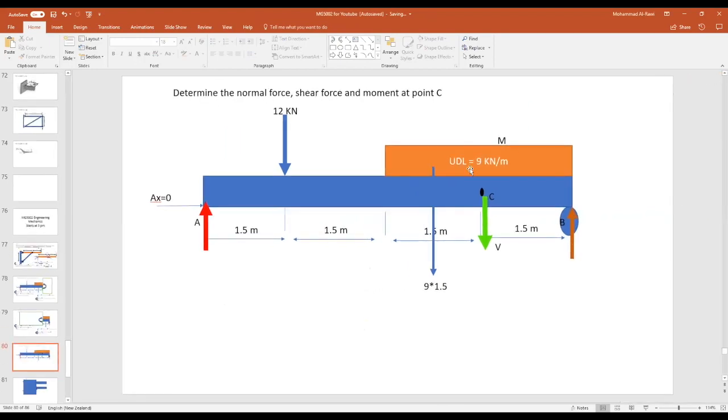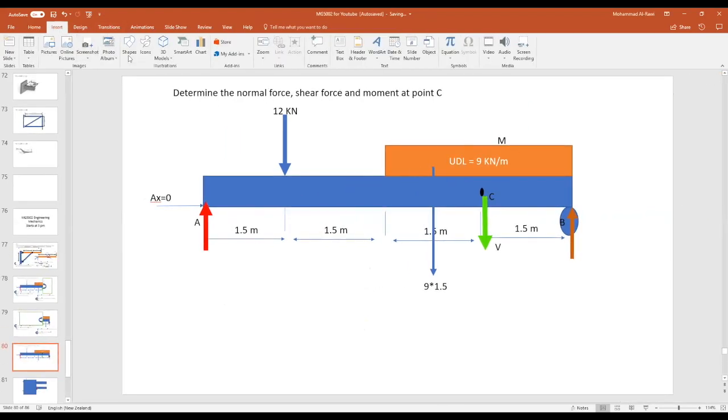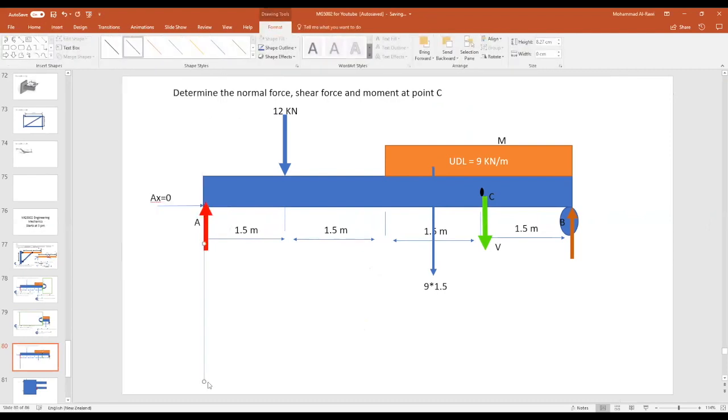All right. So technically, when you get this one, what I recommend all the time, guys, and please remember this in your tests, always project the lines wherever you think there is a possibility of force, and use this as a reference point. You can make it a disconnected line or connected line. Please remember to bring calculators and a ruler, or something to make your drawing tidy and clear so you don't confuse yourself. Hopefully this will help us find a very nice shear force diagram.